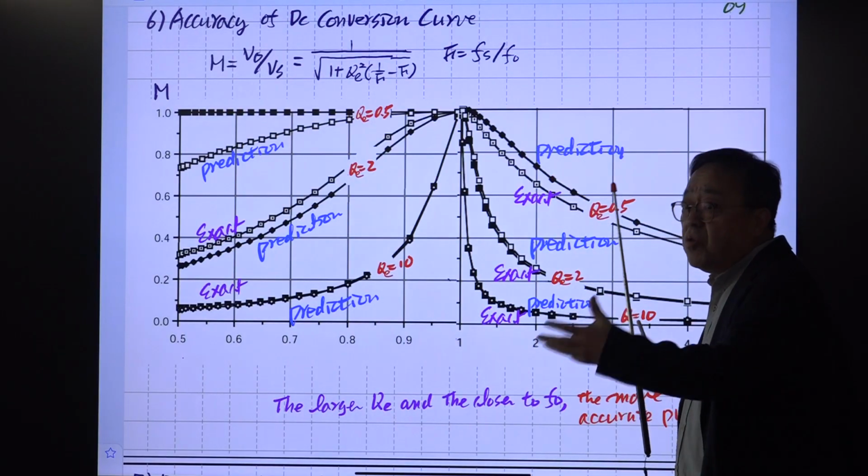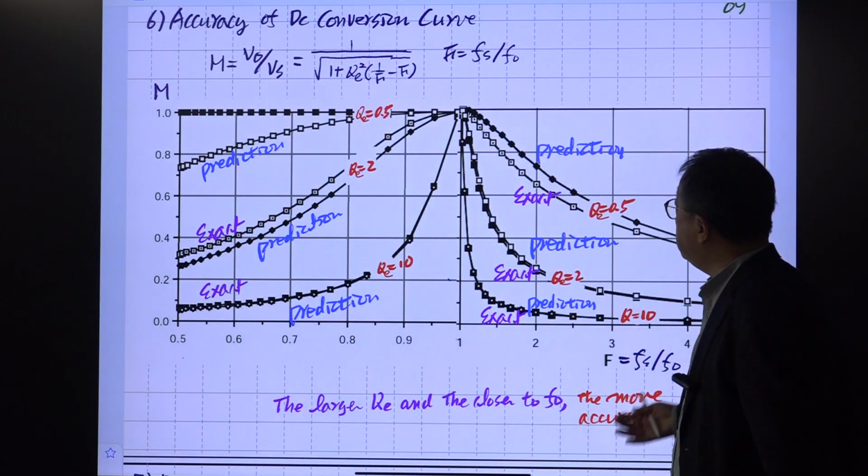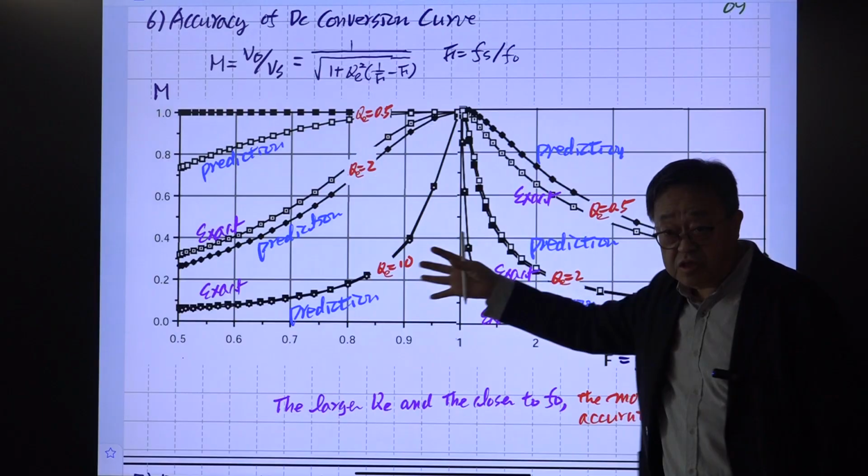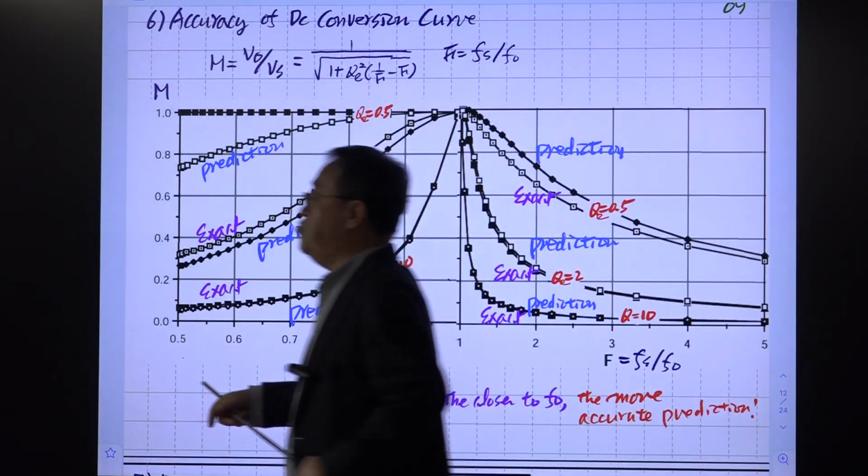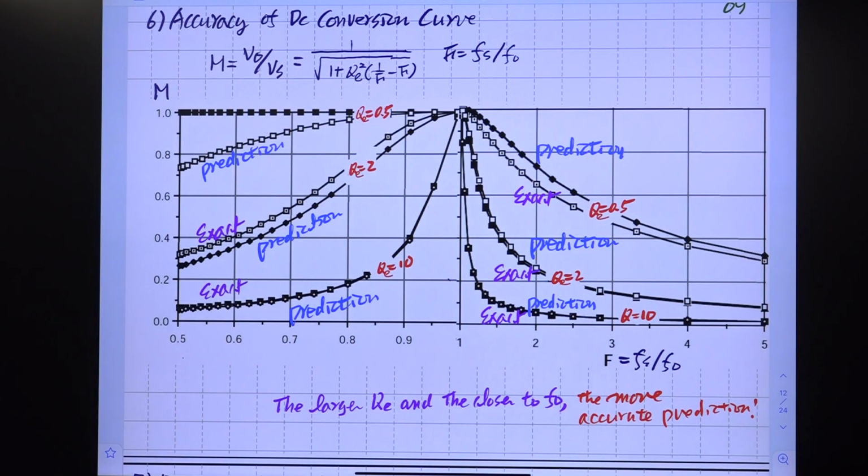But if you enter some strange operational mode, those strange waveforms will come up, and sometimes that induces a huge surge in voltage or current that will destroy your switches. Other than that, if everything is ideal, everything is fine, at least in the simulation.